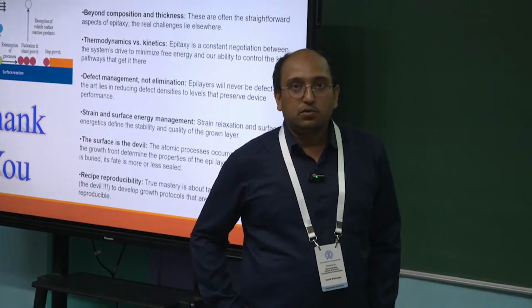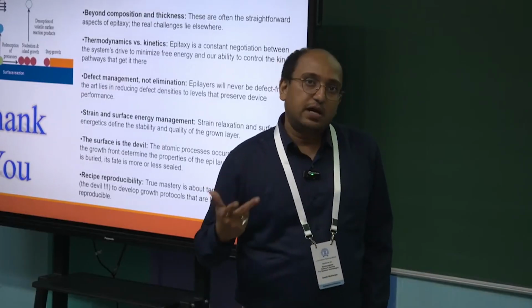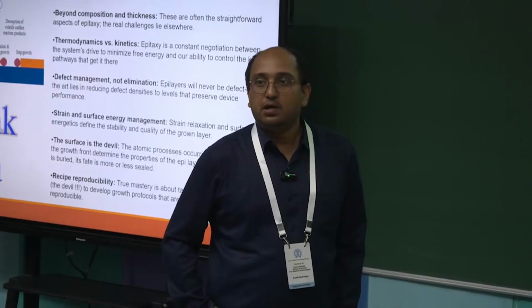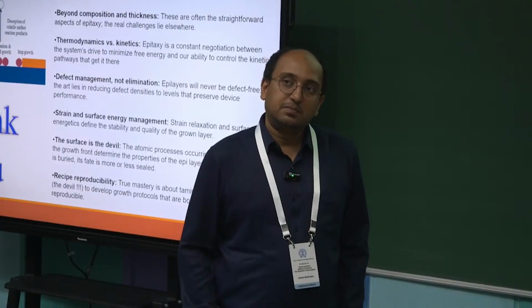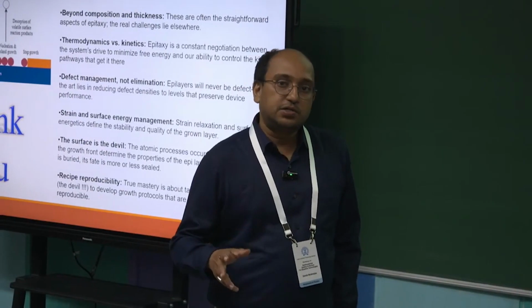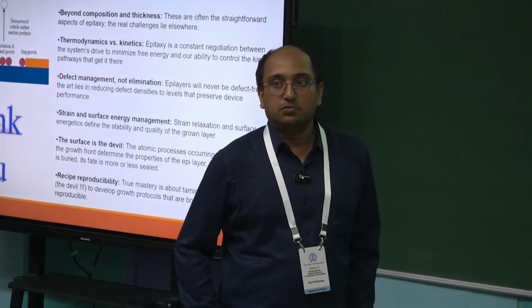Well, there is no real solution for that. You have to quench down. Those are the kind of material systems that we would generally avoid, with a very high degree of thermal mismatch. Like germanium and silicon, there is a mismatch, but it's manageable. Silicon germanium on silicon, it's manageable. But there are combinations where the layer would simply crack if the mismatch is too high.